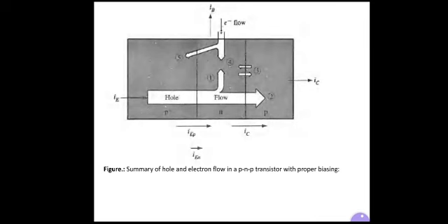And the last one, number 5, is shown in the emitter region, the P plus region. The cross arrow mark shown from the base towards the emitter indicates electrons injected across the forward biased emitter junction.